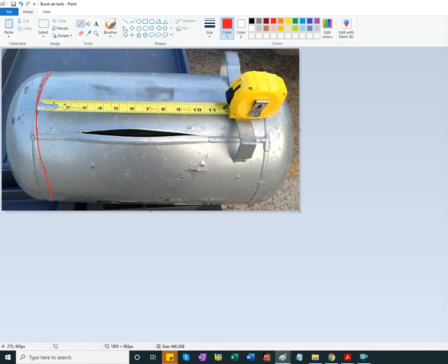pressurized cylinder, and also that the heat affected zone, so you had sheet metal that was welded, and right next to the weld the material was weakened by the welding process, and that's why it burst next to the weld rather than elsewhere. Okay, unless there's some defect, but again the strength of the material was compromised by all the welding process through recrystallization. Maybe it was cold rolled sheet metal, and it burst, as you can see.